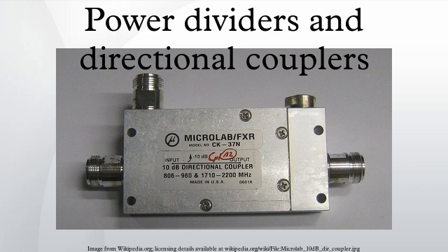Amplitude balance. This terminology defines the power difference in decibels between the two output ports of a 3 decibel hybrid. In an ideal hybrid circuit, the difference should be 0 decibels. However, in a practical device the amplitude balance is frequency dependent and departs from the ideal 0 decibel difference. Phase balance. The phase difference between the two output ports of a hybrid coupler should be 0 degrees, 90 degrees, or 180 degrees depending on the type used. However, like amplitude balance, the phase difference is sensitive to the input frequency and typically will vary a few degrees.